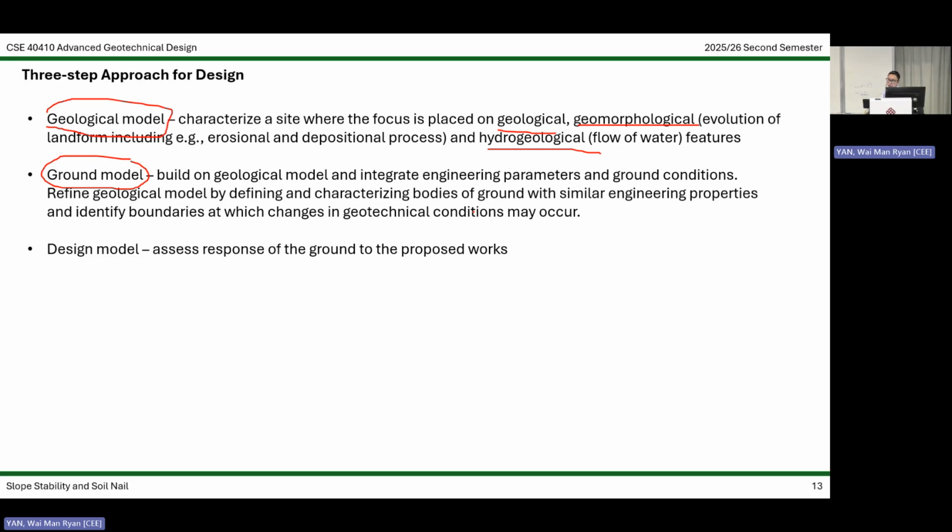How thick is your fill? How thick is your colluvium? How thick is your decomposed granite? How thick is your highly decomposed granite? Where is your rock head? Something like that. And some of the information we could actually deduce from GI. You drill a hole, you log your soil core, so you know from which depth to which depth you have colluvium, which depth to which depth you have completely decomposed granite, for example.